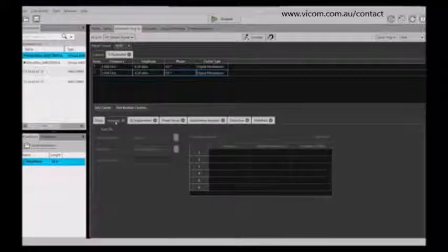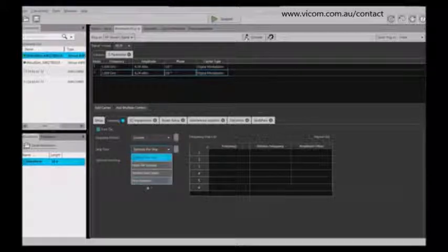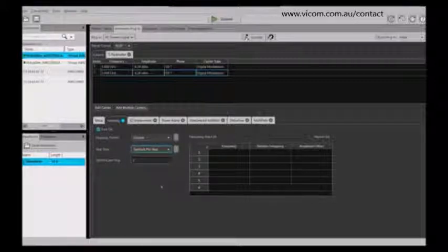You can then go in and have the capability of turning on hopping, such that you can hop from one frequency to another. So you can specify quite a few variables within this hopping characteristic. So you can symbol hop. You can specify your hop duration, your hops per second, basically all the characteristics that you need for your hopping, how many symbols per hop, and then if you have a particular custom pattern, you can use that, or you can use a pseudo random list or a range of hopping frequencies that you want. So this gives you a lot of flexibility.